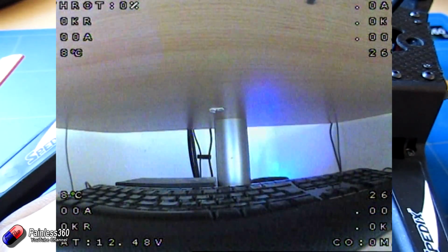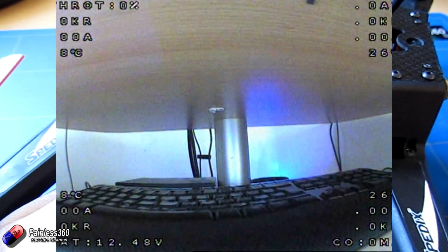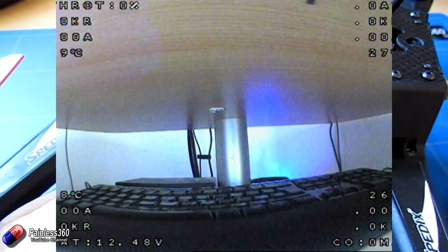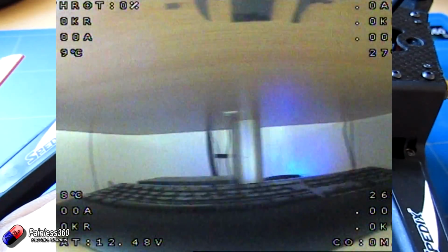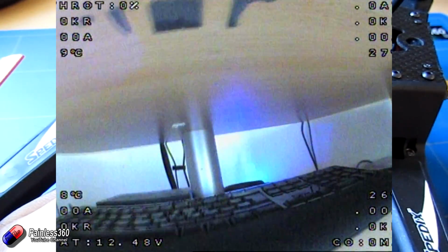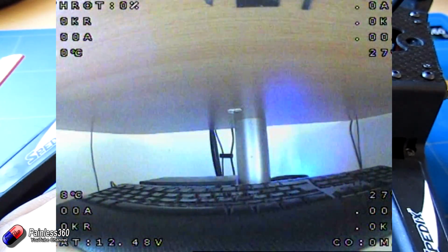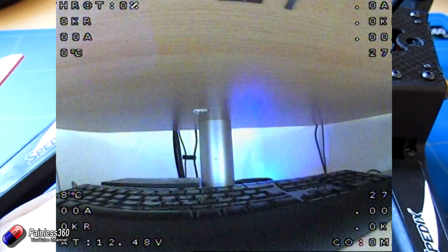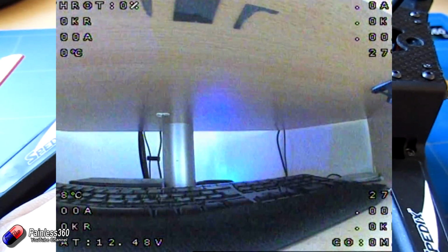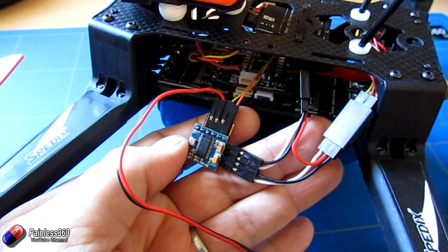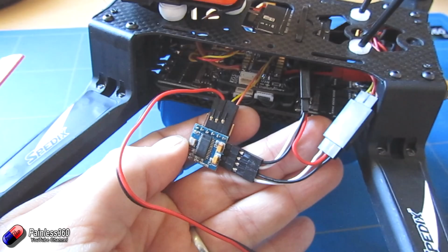Hopefully that helps all of you that are looking to do this and wanting to have a play with it. And now you know the process. The key things here are to upload both the firmware and the font files. And the way it works at the moment is you have to do those in 2 separate operations. The FTDI drivers, if you Google for FTDI drivers, you'll be able to find those if you're having problems with your Windows machine finding and uploading them automatically. And the other tip, of course, is make sure you're using the Arduino 1.0.5. That's the version that will work with this. If you use a later version, then you're probably going to get into trouble.